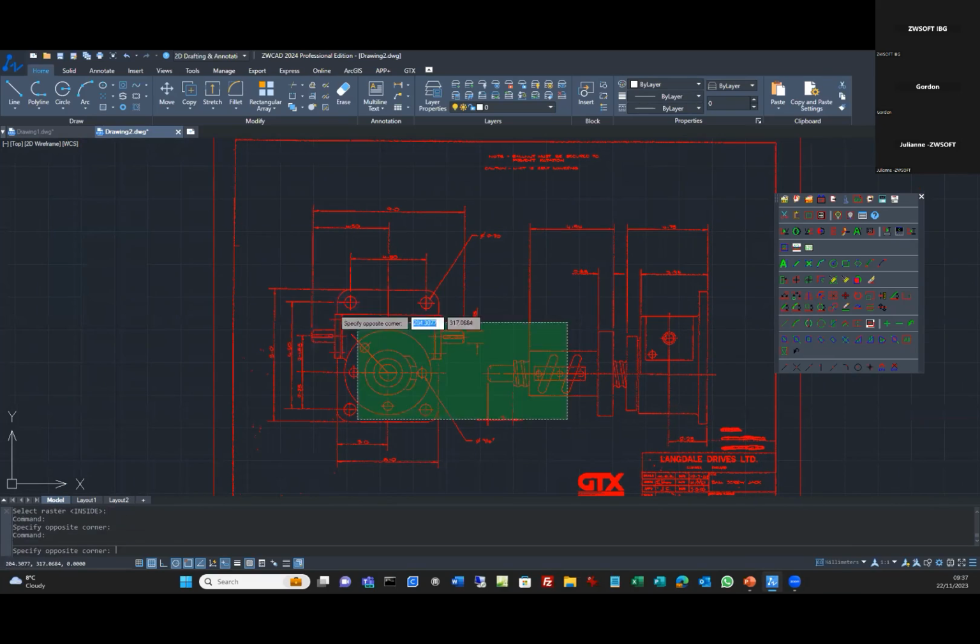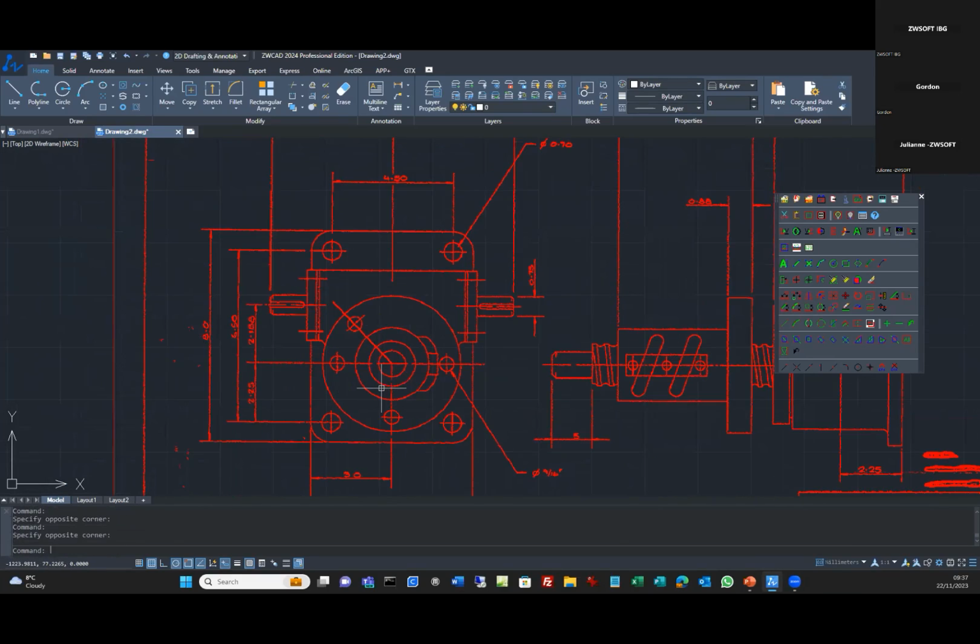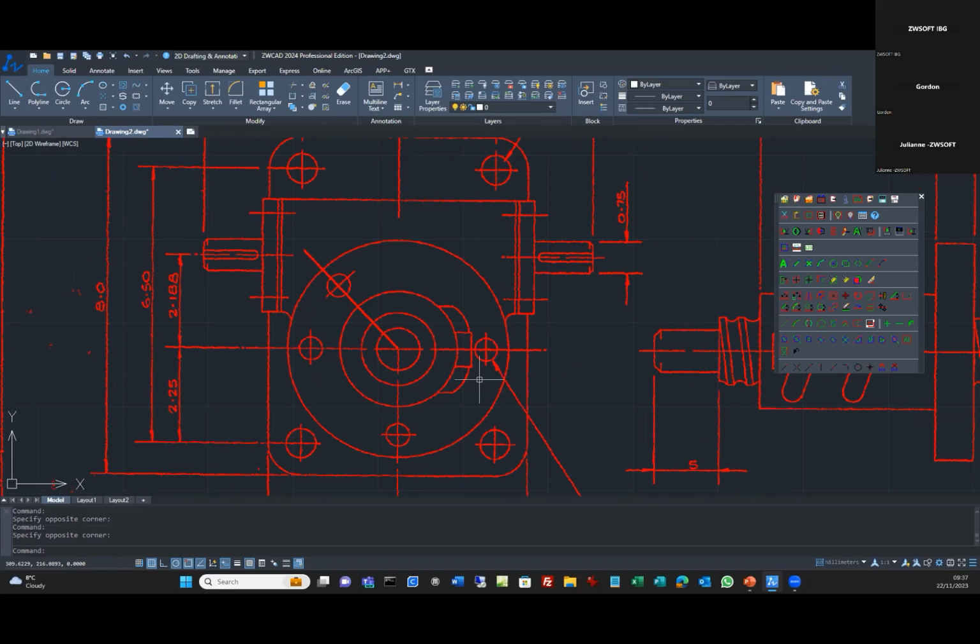As I said, it's still scanned data, so I haven't converted anything within the drawing. Say, for instance, the modification you want to do is rotate this hole up through to 90 degrees. Just to do that simple modification, you don't have to redraw the drawing from scratch. We have these edit tools along here. So I can say rotate, and I can pick my data that I want to work with, so it goes green. I choose the line, I then choose the hole. That's everything that I want to work with. So I hit return to move on through the command.